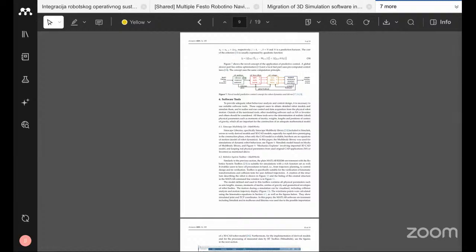The role of CAD tools, NX, Autodesk Inventor, will give you the accurate 3D geometry of the robot. From the CAD model, we can find parameters such as link length, masses, center of gravity, moments of inertia, axis offset, body geometry, collision envelopes. These parameters are very much helpful for the dynamic model accuracy.